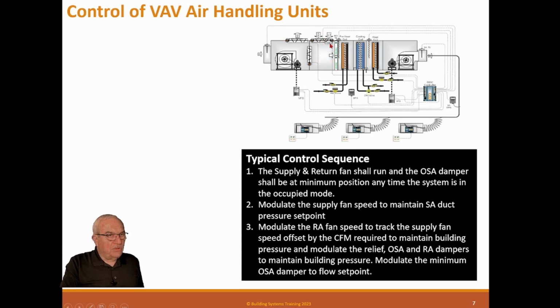If you have higher negative pressure here, it induces a lot of air. So what we do is we normally try to make sure that it has a minimum VAV outside air damper. And then we modulate this, and normally we have a flow meter based on it. There are many ways to try to control this, but the very best is to put a flow meter on it. So that damper is controlled to the flow meter. And the reason is that for ventilation air, we want a constant flow, not a variable flow. If you have this damper fixed, and these blowers speed up and slow down, then you'll have variable intake air. And that's not going to meet the code or the standard for ventilation air into the space.